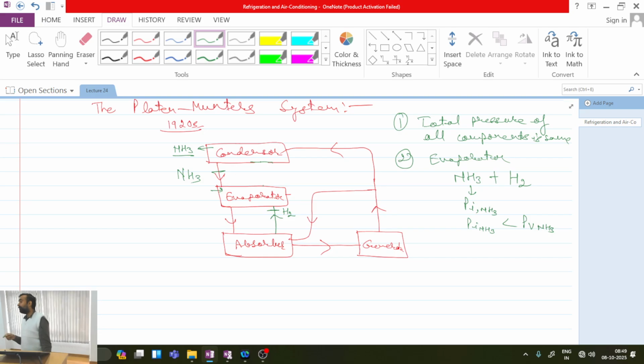But if my air is not saturated, what does it mean? It means that the partial pressure of water vapor is less in comparison to the saturation limit. In that case, what will happen? Some water will keep on evaporating till the pressure reaches the saturated condition. So I will find that the water level in the glass keeps on decreasing. Is this clear?